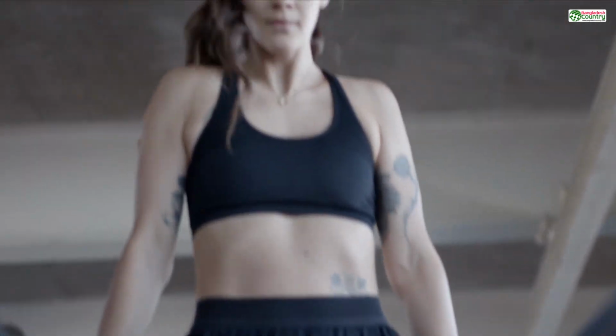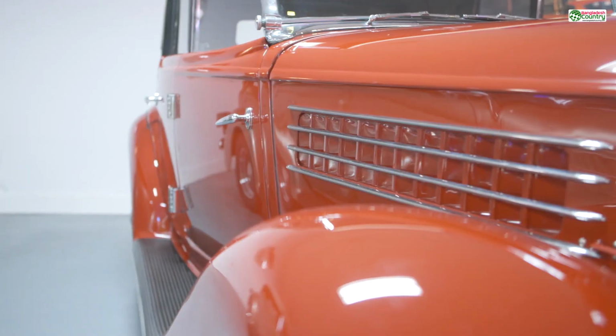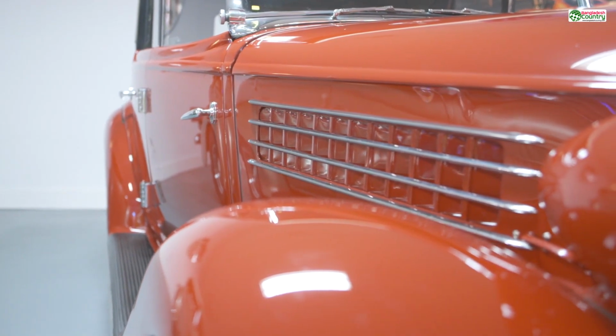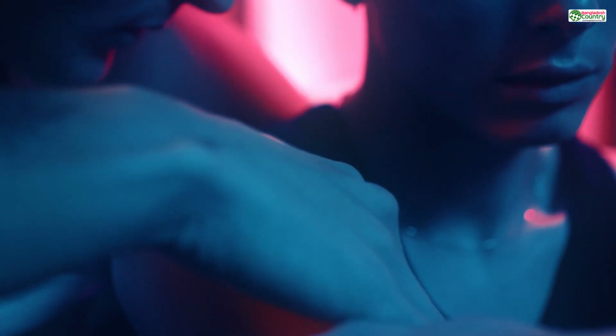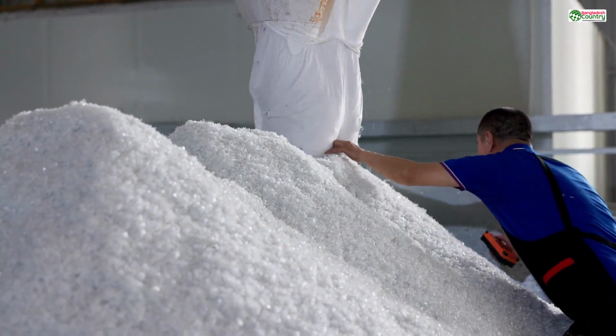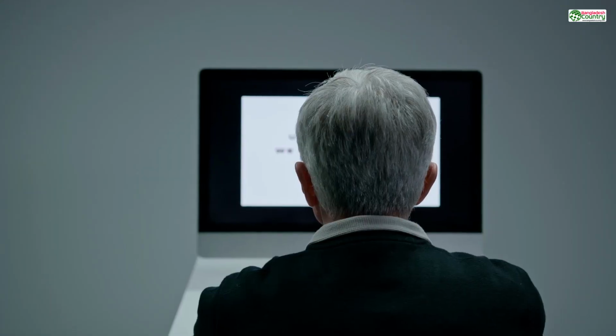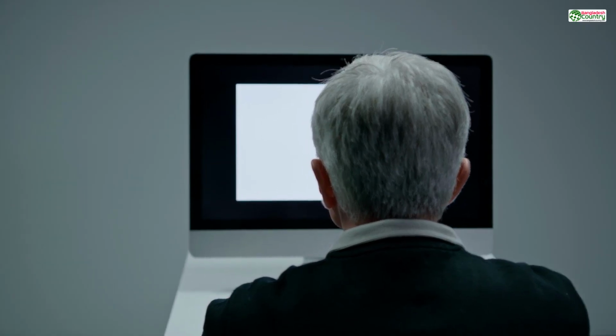But what if you want the best of both worlds? Enter polyethylene terephthalate glycol. It might be a mouthful, but think of it as the all-rounder. PETG is a fantastic compromise between the ease of printing of PLA and the strength of ABS. It's significantly stronger and more durable than PLA, but less prone to warping than ABS. It has a bit of natural flexibility, so it's less likely to shatter on impact.